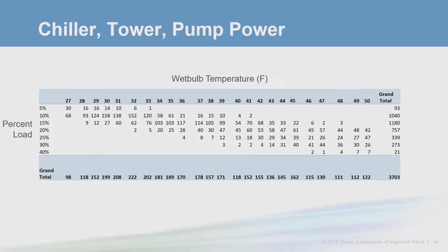If our tower has sufficient flow turn down, we can spread the flow over more tower cells and slow the fan speed down as low as possible. 90.1 requires a 50% flow turn down, so we should pick a heat exchanger that can handle the minimum flow of 2 tower cells. I'm going to use a tool that we have for predicting cooling tower performance. On a real job, you would get this from the tower provider, but since this is a hypothetical case, I'm going to use a different method.